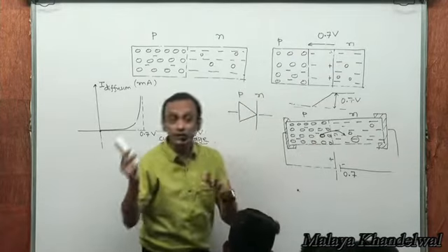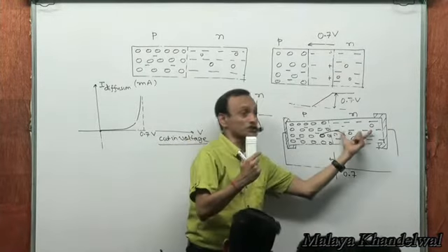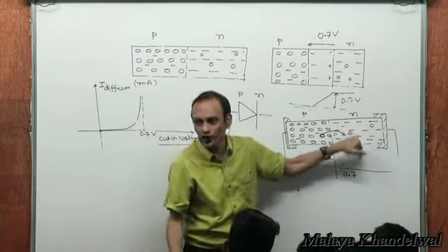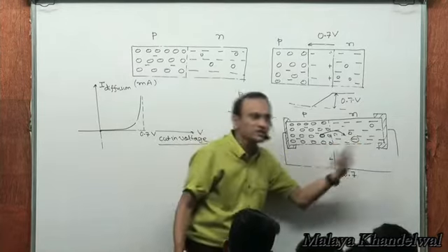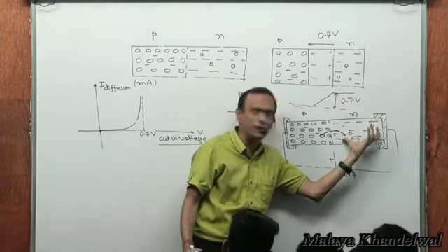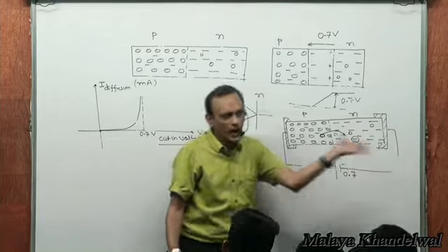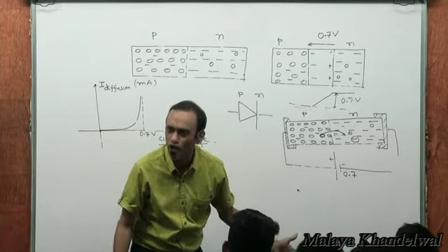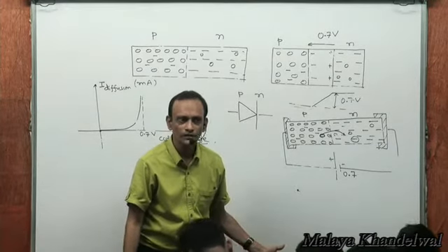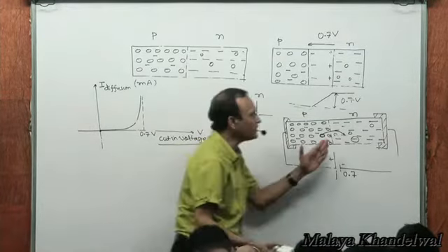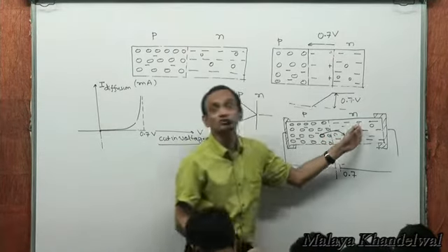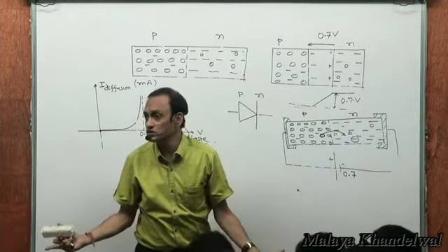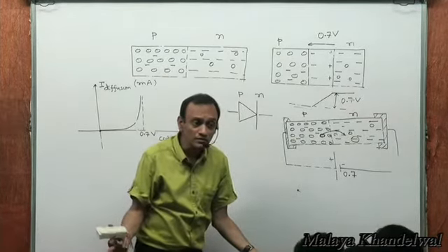So one thing you might want, the fact that the concentration of holes here is growing is a myth. Because the hole comes into this region, but it's recombining with an electron because there is such a huge population of electrons here. One or the other electron will consume the hole. There would be annihilation of the hole, right? And therefore, the increased concentration of holes that you are perceiving here is nothing more than a figment of your imagination. That far and no further, right?